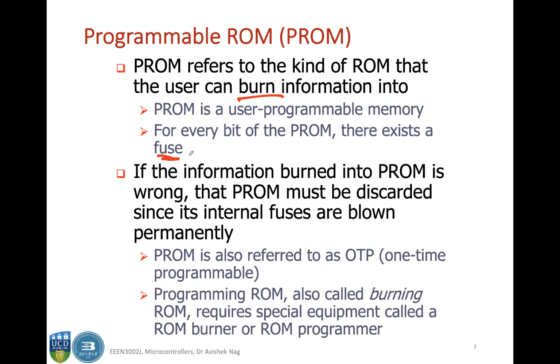You are basically burning that fuse to write information in that ROM. When you have a fuse, let's say that is a 1, and when you burn the fuse, that is 0. In that way you can store binary information in the ROM.